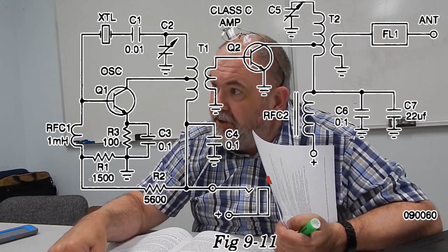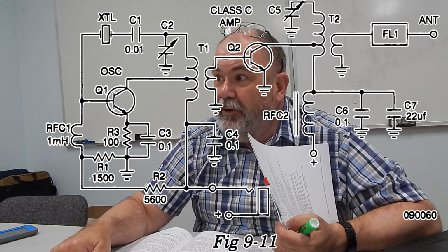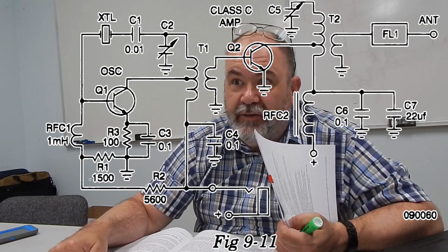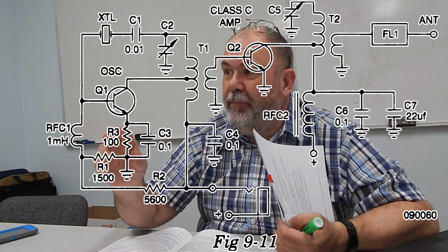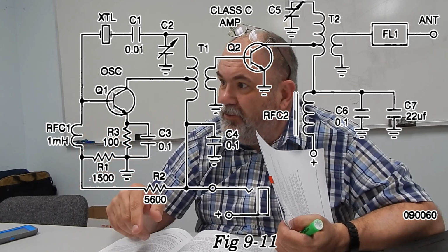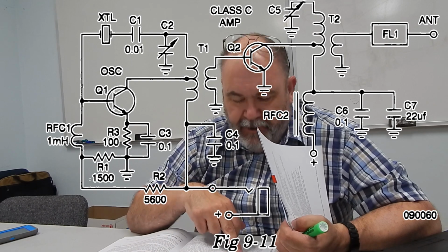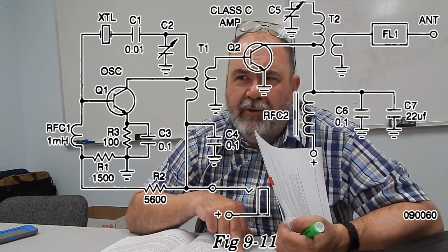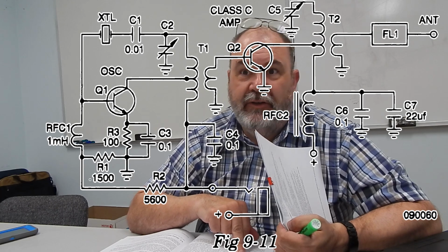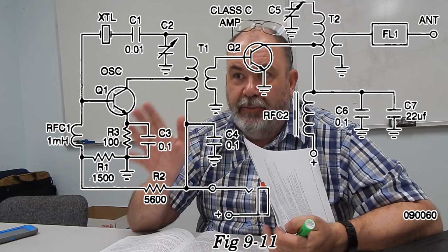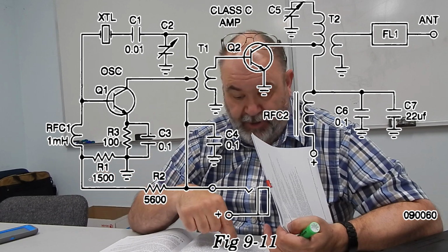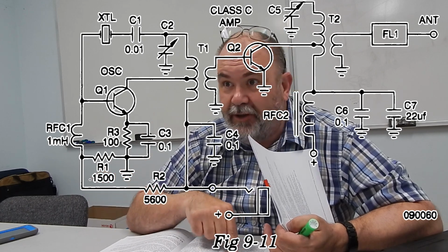So when you key, that's like a power switch. When you key down, you're turning on the oscillator, and when you key up, of course, the power is removed, so the oscillator dies. Okay? That's a really bad way to do things, because once again, oscillators like to sit there running dumb, fat, and happy. They don't like to be switched on and off and stuff like that.